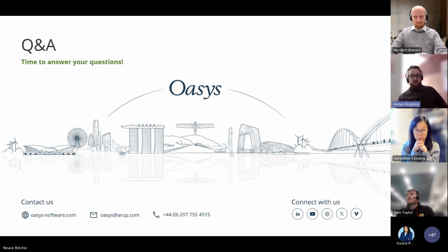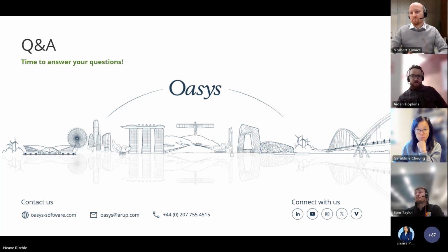So when you're thinking about your trough being shallower and wider at surface, XDisp will calculate that steeper, narrower one at depth if you put the right inputs in and select the right curves, and that's all covered in the help. And I think Geraldine already talked about excavations and about how you can input your excavations to give you the results at depth. Thank you.